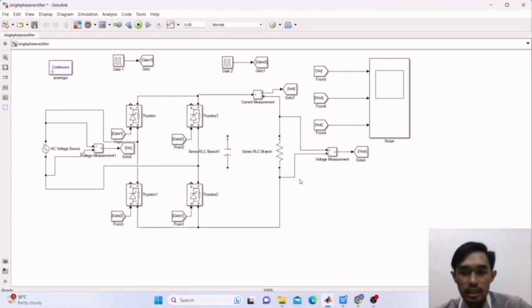A bridge rectifier is an electronic circuit that converts an AC to a DC voltage. The basic design of a bridge rectifier involves 4 diodes, which here I replace with transistors in the Matlab Simulink, arranged in a diamond pattern. The AC input voltage is applied across two terminals of the diamond pattern, while the DC output voltage is taken from the two remaining terminals, here, negative.